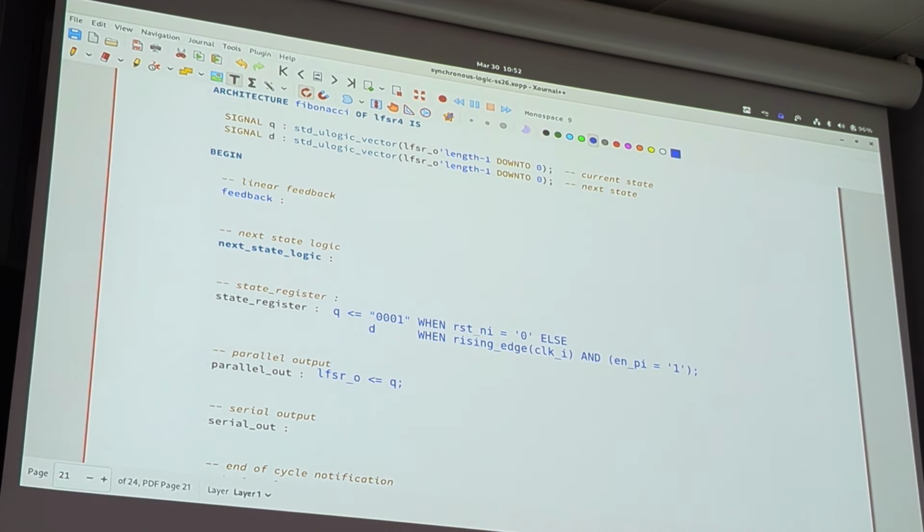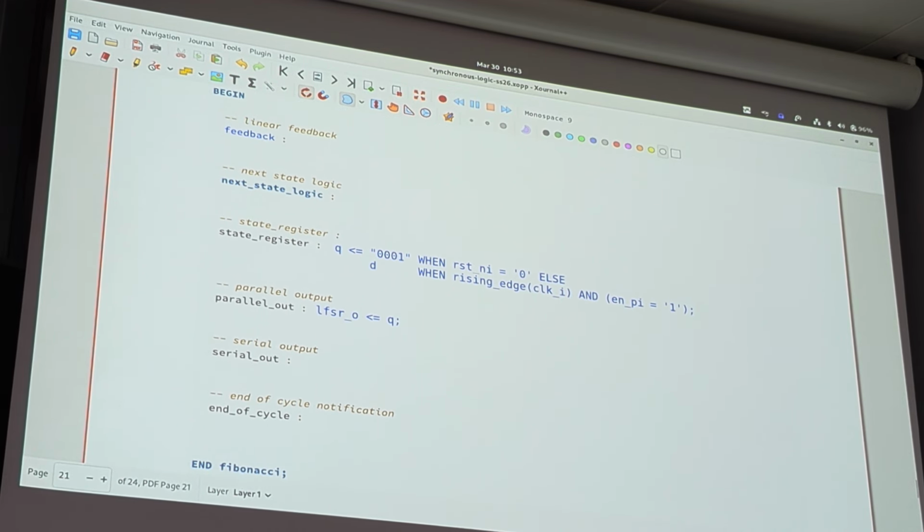Why go to the trouble of using the LFSR length when defining the signals? When in the state registers we again use a fixed length register. Just to show you how to use the attribute. So step by step I'm trying to introduce you to more and more elements in modeling. Of course, in that case, just writing 3 down to 0 would be sufficient.